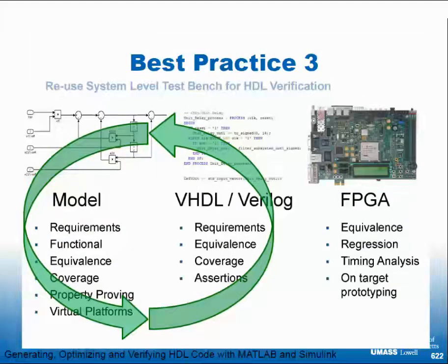So you have this system on a chip that you're building. It has processors on it and all the kinds of things that go into processor design. It has an Ethernet MAC. I'm just using that as an example. You can spend a lot of time on an FPGA getting an Ethernet MAC to work, to get it to pass static timing, to get all the configurations right.